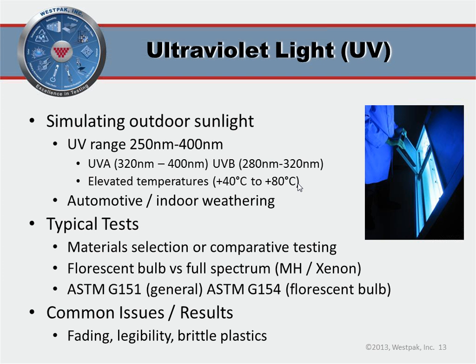The tests themselves are typical material selection tests. So you can see in the picture here we have a whole laptop. That's sometimes done, but usually we'll use little swatches of all the materials. With the laptop like this, it may be important to actually test the inside of the laptop. The keyboard, all the little buttons and components may be made from different plastics, different printing processes. Test all of that comprehensively. It's the little inside stuff that gets them; people use the right outer case material, but the inside parts fail.